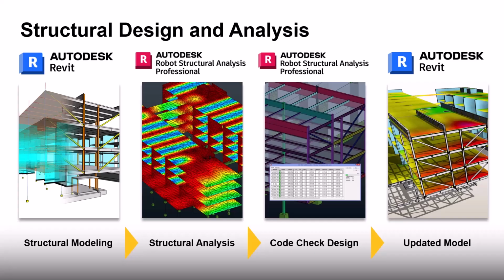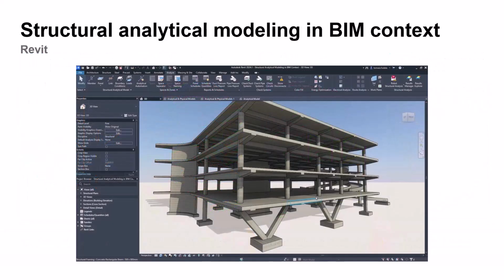It's more versatile than before, able to represent any object you need. And third, just like in traditional analysis tools, we can also start directly with the analytical model and use Revit parametric capabilities to define it. And finally, we have full interoperability with analysis. Results come back to Revit when design decisions are captured and ready for detailing downstream.